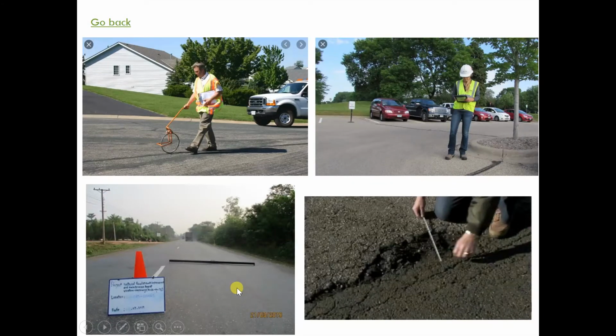So the inspector will need to go to the site to check the site condition, to find where the defects are. They need to measure and find the location as well. Previously, they had to mark the chainage of the roads, and they can identify where the defects are. Then they can see the cracks, the depression, the rutting, and they can measure the cracks as well.